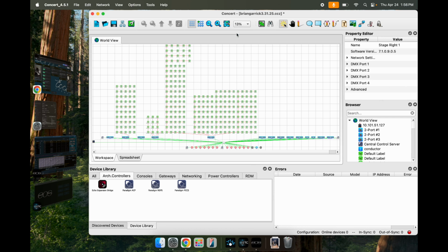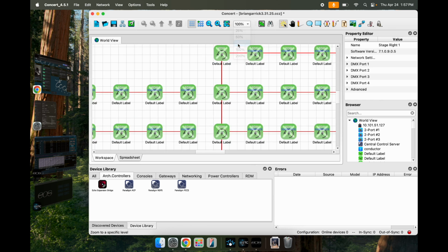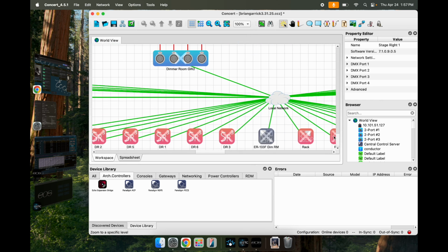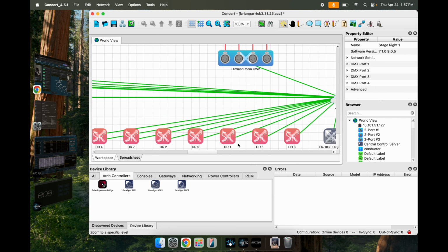Going into talking about sensor racks, because we do have ThruPower modules, Sensor3 racks made by ETC, you can actually control all this in the Concert software, so you do not need to physically take things out and put things back in. So I'm going to show you a little bit. I'm going to zoom in, and they should be here on the bottom. You can see they're labeled dimmer rack, but they are sensor racks. Dimmer rack just because it's more conventional.